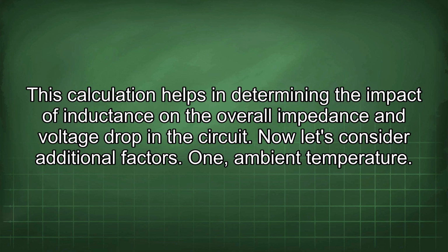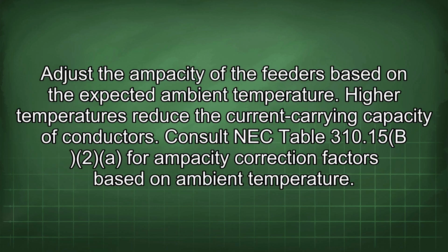Now let's consider additional factors. 1. Ambient temperature. Adjust the ampacity of the feeders based on the expected ambient temperature. High temperatures reduce the current carrying capacity of conductors. Consult NEC Table 310.15(B)(2) for ampacity correction factors based on ambient temperature.